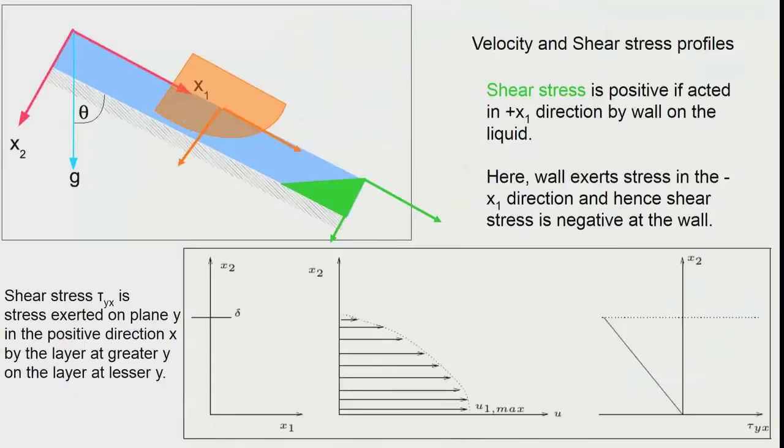So, when we plot, it looks like this. The parabola has a shifted edge bit. So, this is how the velocity profile should look like, and here I have drawn the parabola in a flipped direction intentionally to show you the nature as a parabola, and you can see only half of the parabola is actually applicable, and the slope here is 0 when you look at here in this direction. So, dou u by dou x2 is 0, okay,